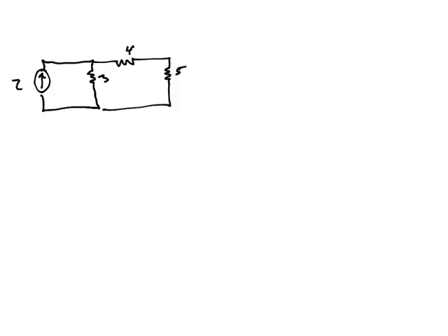What do I want to find for this? Let's say, well, I'll leave that alone for now. First step, when we do nodal analysis, choose a ground. I'll choose it in red. Down here is my ground. So that means all of this stuff in red, all of this is the ground.